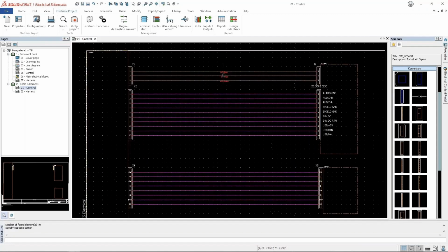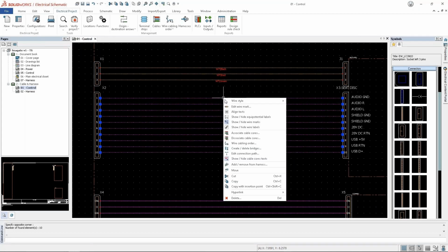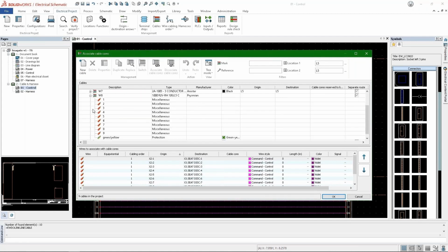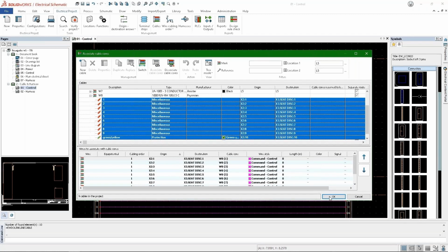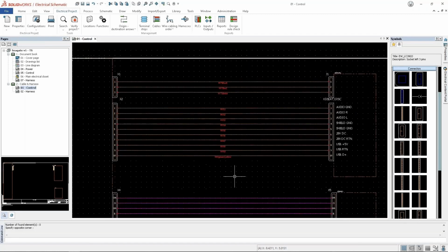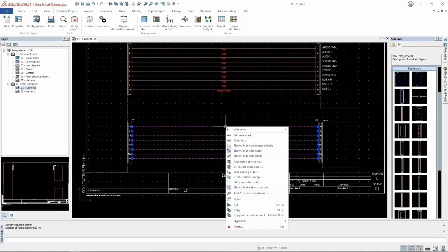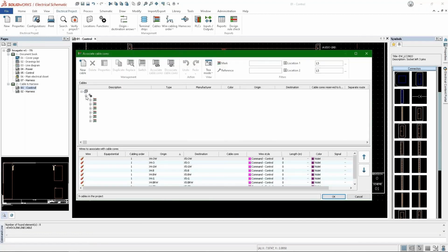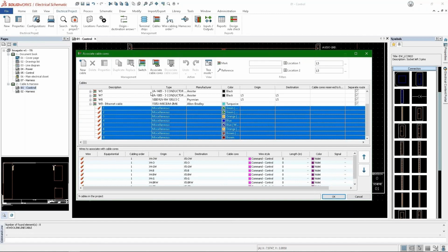Notice again, right there, the cable designations are found there with any descriptions for the cores. So I'm just going to go through this same process of further defining the connections within this cable. As soon as those are made, it understands to and from, and it populates a lot of that metadata into these wires and into these cores and cable. And we'll take a look at a little bit of that here in a second once I finish associating W9. It's a super powerful tool.